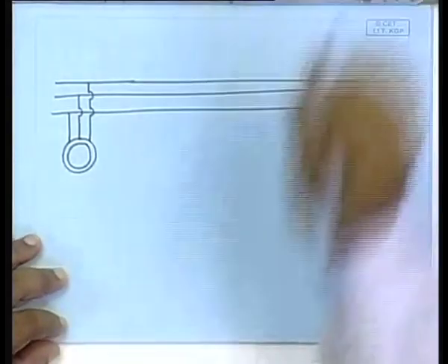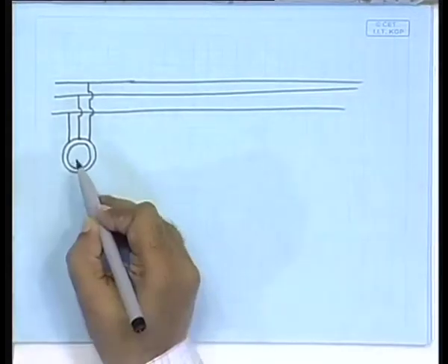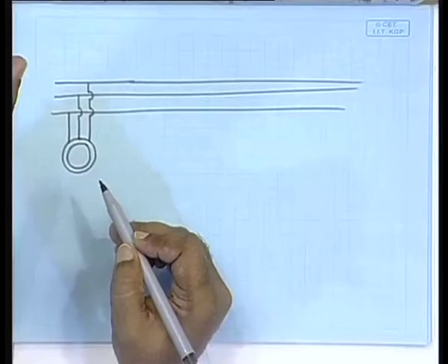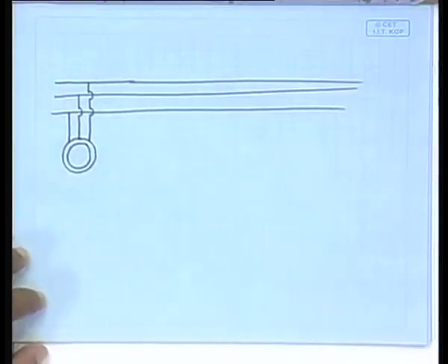In order to avoid this problem, what is done is, so far we were considering squirrel cage machine, that means the rotor is self-contained and shorted by itself. Now, in the alternative arrangement, the rotor is also wound, that means you have actual windings which are taken out. You can imagine it as something like this. I will draw in a separate page.